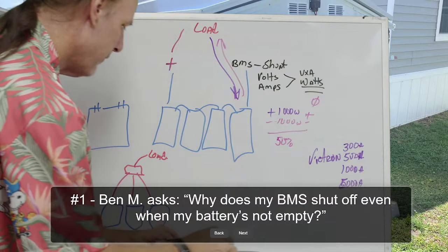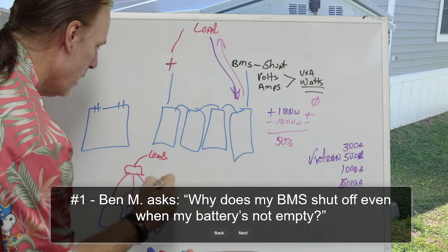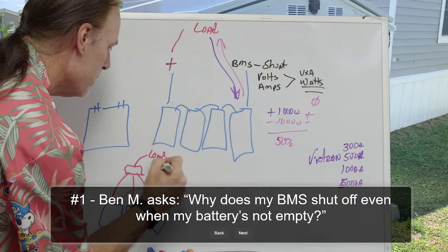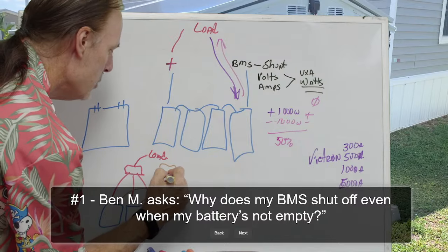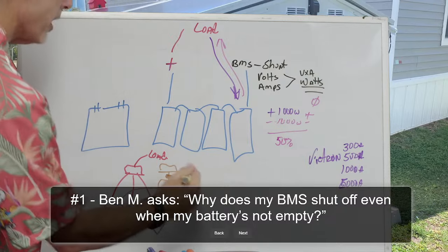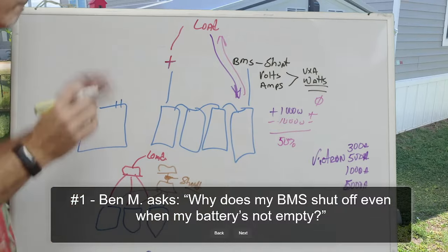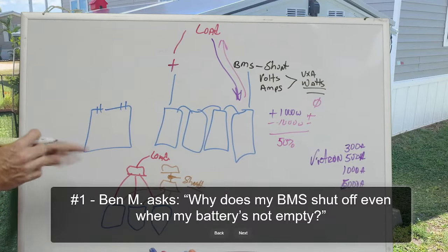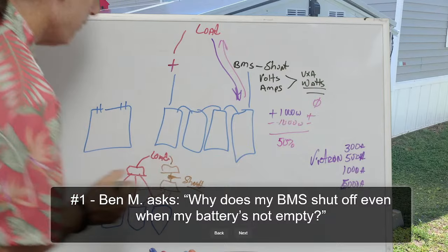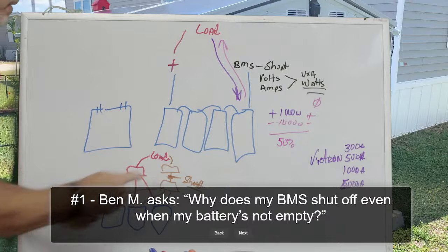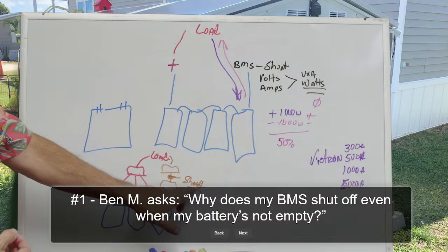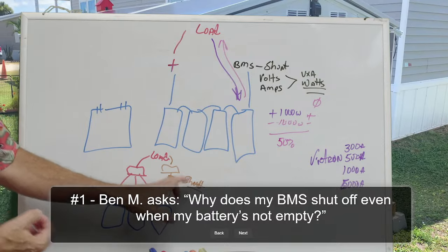And then on your negative bus, you run it through a shunt to a second bus and you put the shunt in right here. Now this would be like a Victron shunt that has a much more precise calculation and measurement of the power, and then your load would run off of that. This shunt, being more precise, being of higher quality, and being of a lot more accuracy, would give you a valid reading of what it is.